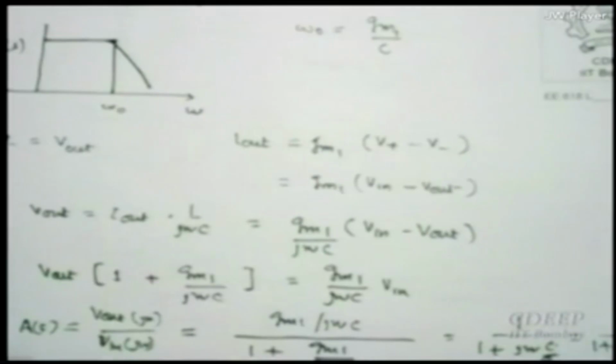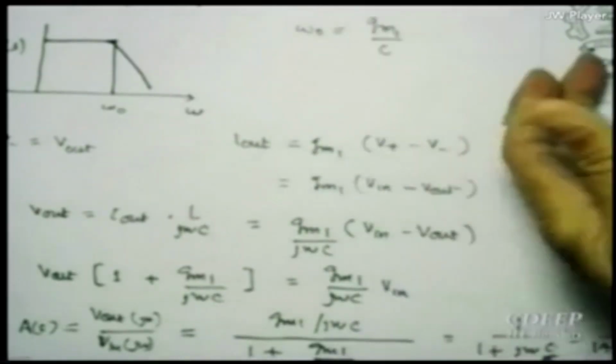If the curves are sharper like this, somewhere at very small values, the C values can't be figured out. Varactors are normally used when you are looking for a lot of difference, that is, in a VCO we will use it, for max and min values. So I will use one value here on the curve and one value on the other side.